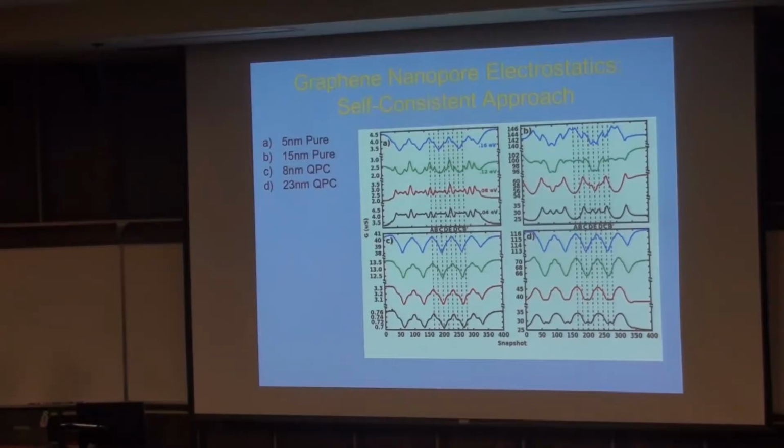But if we change the Fermi level to 0.16 eV, the conductance fluctuations increase to almost 3 microsiemens. The effect is even more enhanced over here. For a very low Fermi energy, we see almost 10 microsiemen fluctuations, and for the highest Fermi energy, we see a smaller 3 microsiemen fluctuation.